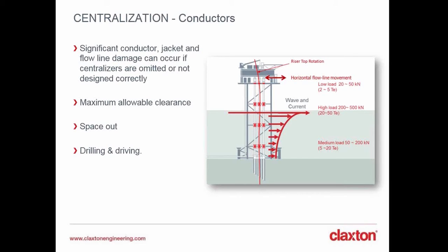There's also offset between the well and the jacket. And as we covered in the previous slide, if you control that centralization during spotting, that should be minimized. But that's something else that needs to be considered. There's also the compression from surface loads, and that is going to be of particular importance on the lower section of the conductor, requiring support to prevent collapsing, but it should still be flexible enough to allow the tieback, if necessary, from seabed to surface.